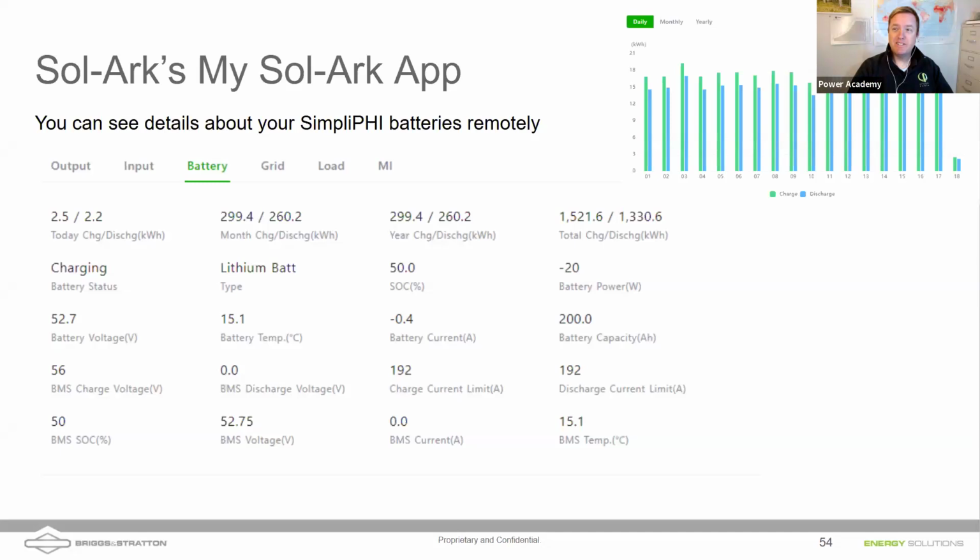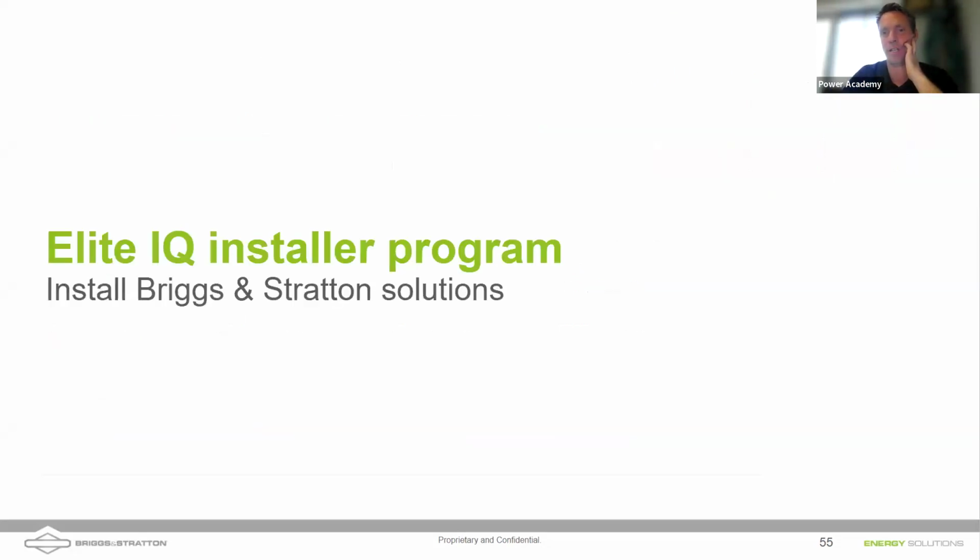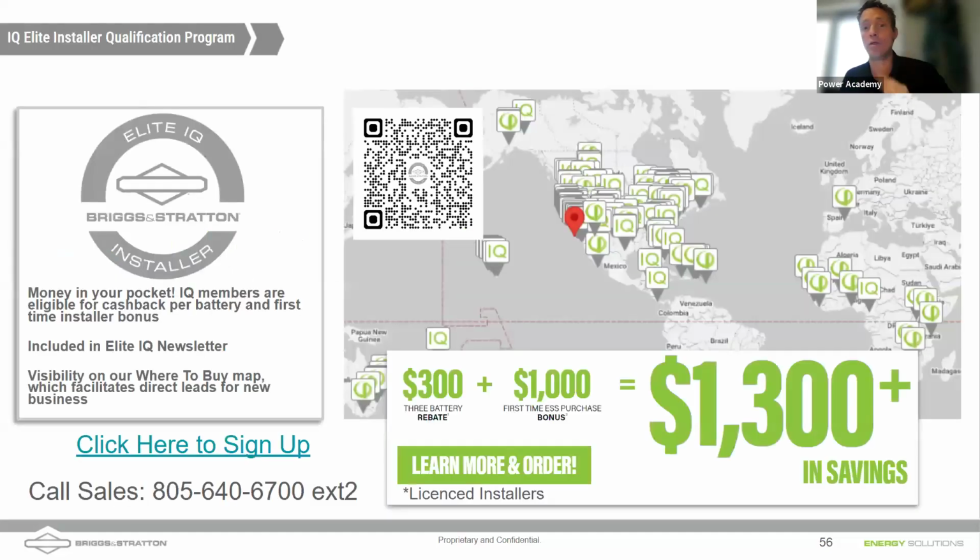Temperature? Nope, there's inefficiency, right? So you're always going to use a little bit more energy charging than you're going to get out on the discharge. We mentioned before that about 5% of the energy with a DC coupled system is lost due to inefficiency. With an AC coupled system, you're looking at a little more, about 15%. And of course, those do depend on charge rates, etc.